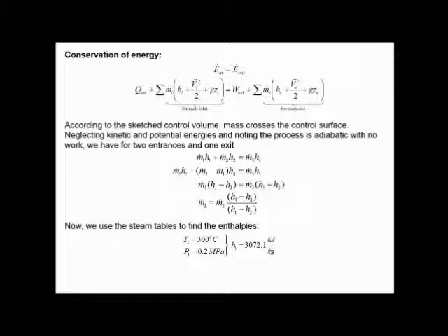So m1h1 plus m2h2 equals m3h3. By substituting the values and rearranging them, we get these values. Now from the steam table we get T1, P1 and h1 respectively. Now the things become simpler when we have all the values, we have the concept, we have the formula, just substitute them and get the answer. So m2 equals m3 minus m1, it comes out to be 17.18.